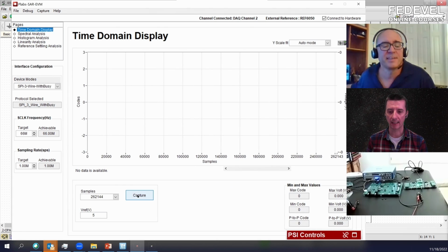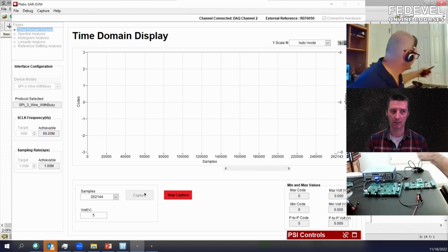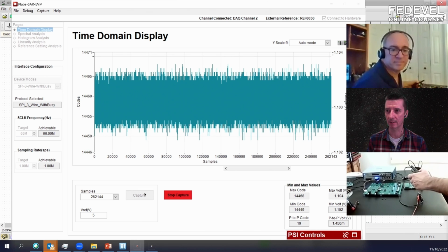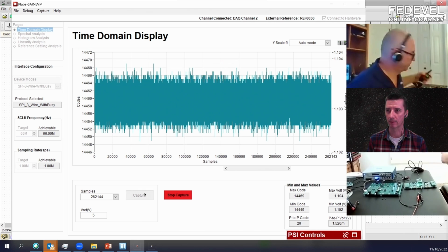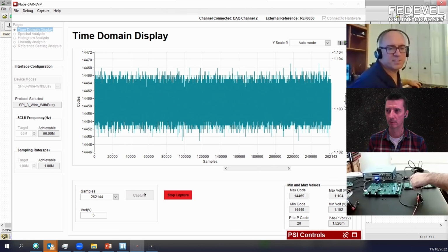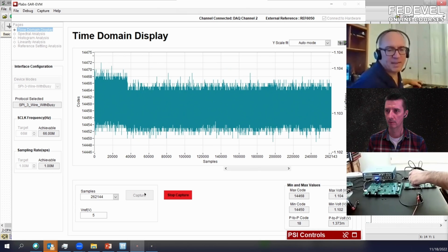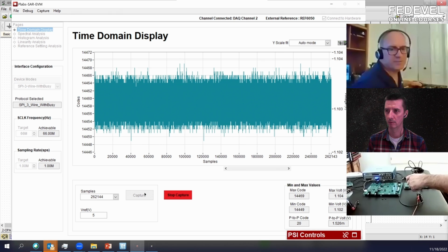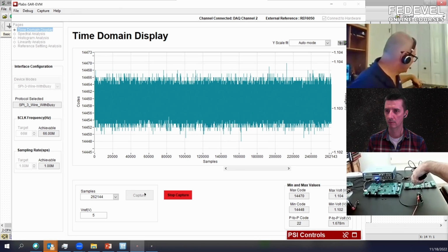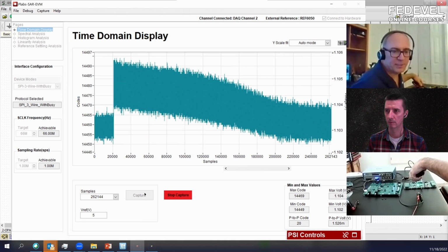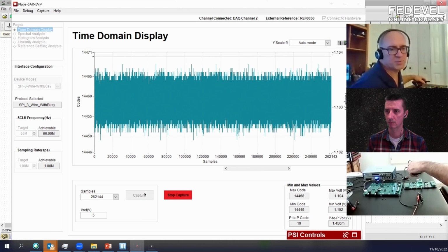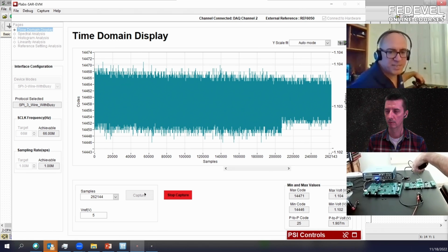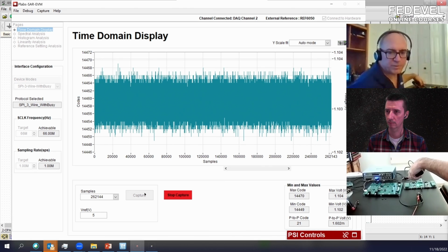So basically, if we need to recognize whether there is intrinsic or extrinsic noise, we can have a look at this noise distribution and see which one we have. Yeah, and you can look in the time domain as well. What happens when you apply an RF signal to a low frequency op amp like this 1 megahertz amplifier is it shifts the offset. As I mentioned, some devices have better rejection of this RF than others, and that's what the EMIRR, electromagnetic interference rejection ratio, does. You can see in some of the examples that we're shifting the offset.